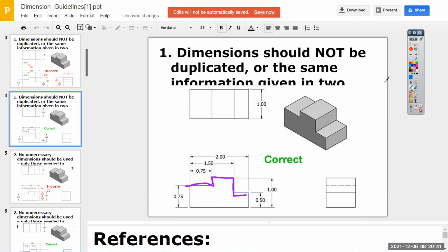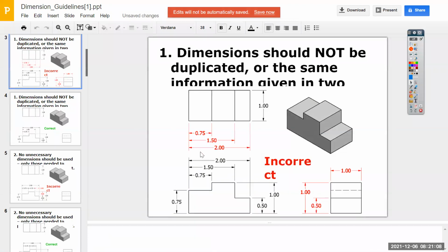And there's benefits for both, but we're just going to do the learn dimensioning on the puzzle cube. Regardless, you would want dimensions to go where you can see what they're actually dimensioning, where on the top view here, these dimensions, and I'll show you the bad one here right above it.